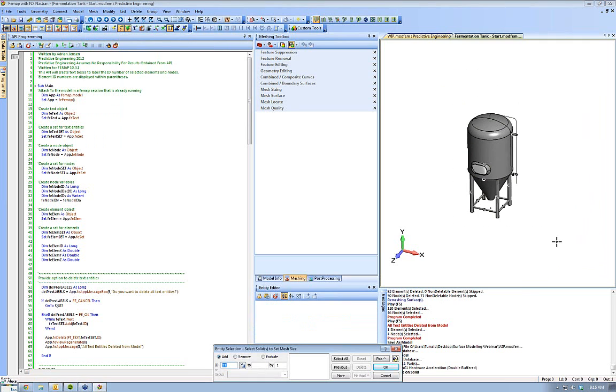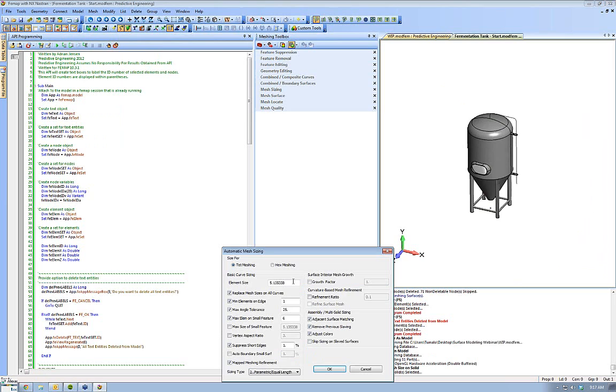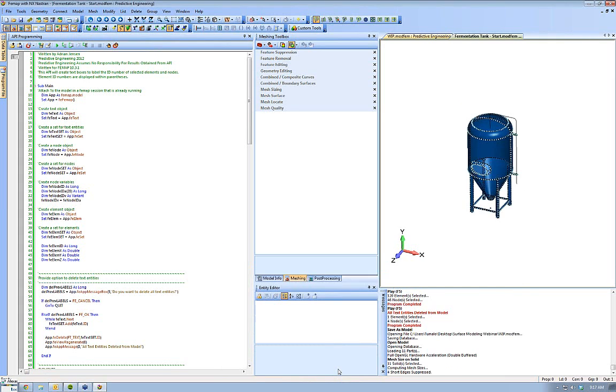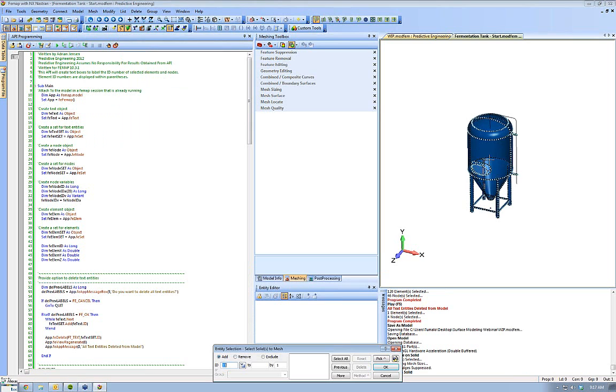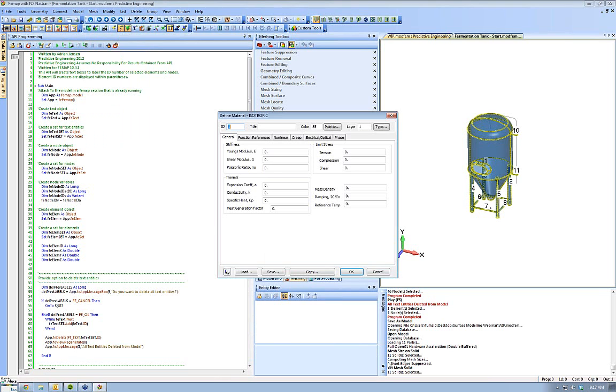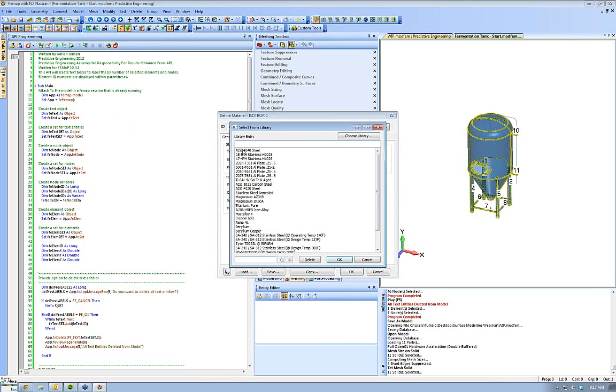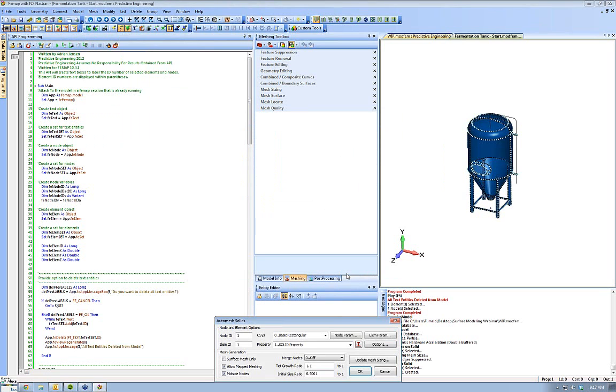So we want to mesh all of these solids here. And our mesh sizing, I think it was even smaller. It was something like 4.8 maybe. So we'll use the same mesh sizing that we did for our plate meshes. Okay, and then let's mesh. We're going to use a solid mesh on these previous solids here. We need to pick a material. Okay.